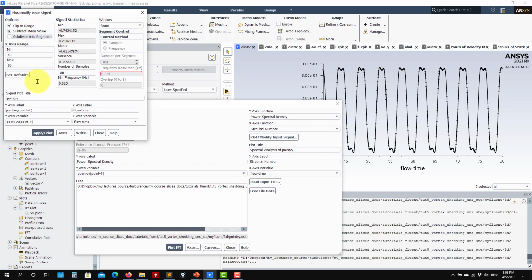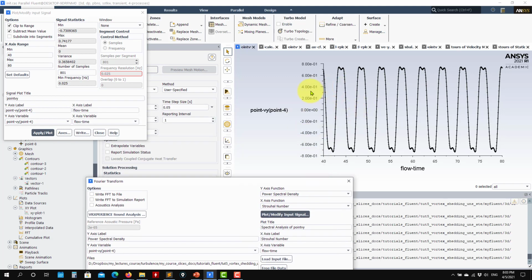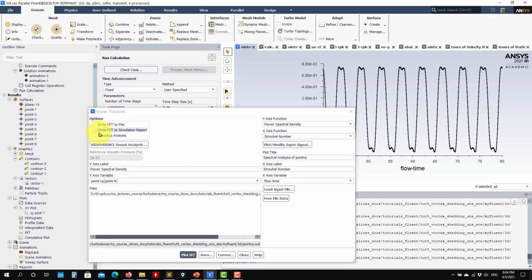So as you go here, subtract mean value, see that you are subtracting your mean, and here you have, this will represent your fluctuation. But in this fluctuation, also you have some peaks that you need to detrend this data, okay? So this is something particular, later we can talk about that, but see that we subtract this one, so in theory this should be the fluctuation, okay? Then you need to compute the turbulent kinetic energy, that is the square plus all the components or whatever, or you can get the 3D spectrum or the 1D spectrum. And because later we work on that.